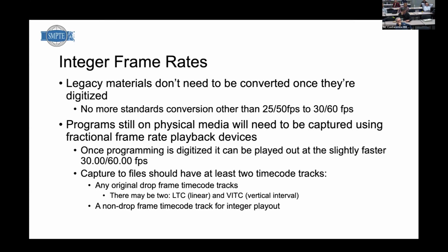But in my role as being a passive throughput transport provider, you remember our days at MCI, where a network clock would interfere with the first HD signals because the manufacturer's clock and the network clock couldn't synchronize. Well, we've gotten to a point where I have two manufacturers that do auto sensing, and I can do everything from ASI, SD-SDI, HD-SDI, 1080p, 12 gig, 4K. Different frame rates? One frame rate.